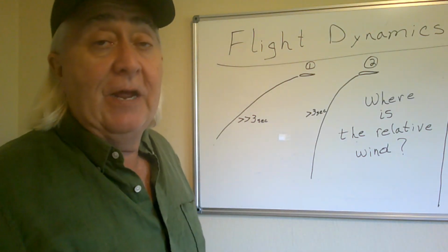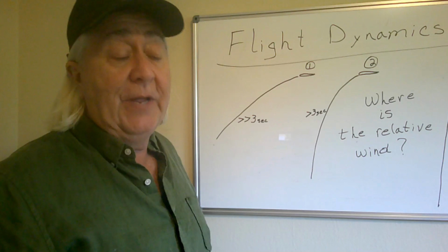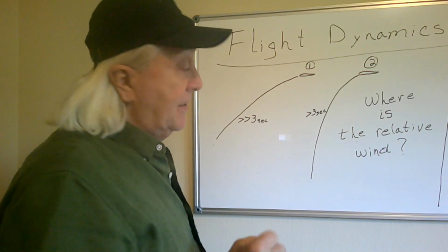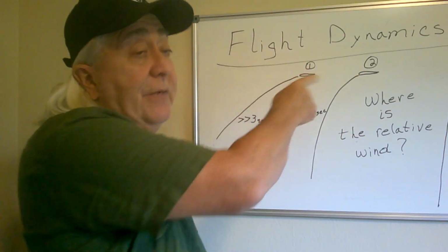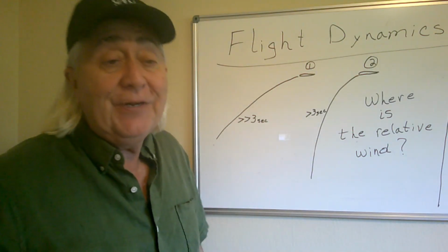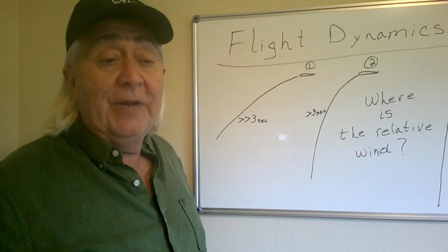You're putting the flap down, and usually when you're on approach, you put it down in notches. You add a little more flap, add a little more flap. And he's a very experienced pilot. He would know to do that. Well, you got plenty of time here to say, oh, this is not working. I put on 2 notches of flap and I don't have any more elevator command.